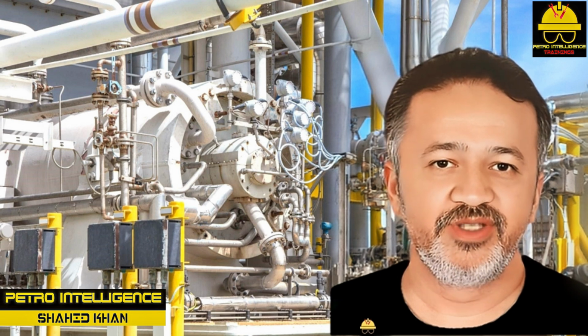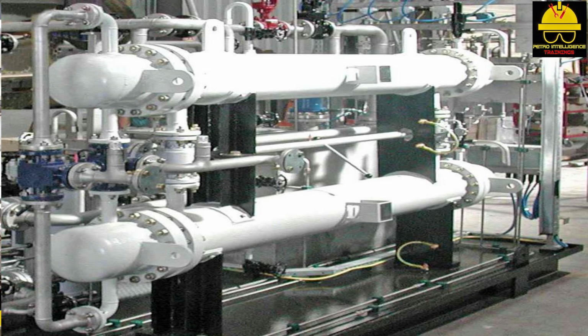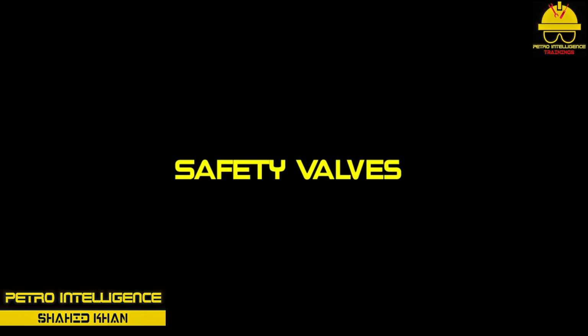Intercooler and aftercooler heat exchangers. The compression of gases creates heat in a compressor. Shell and tube heat exchangers, intercoolers and aftercoolers, have been added to the design to control high temperatures. As gas is discharged out of the first stage of a compressor, the intercooler lowers the temperature. This cooled gas is directed into the suction line of the second stage compressor. As this gas is compressed, creating more heat, it is discharged into the aftercooler before going to the receiver.